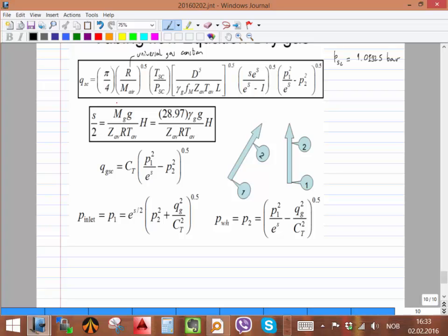So when you say that the gas flow is always turbulent, then the friction factor becomes only a function of the roughness and the diameter. And for tubings, usually from the manufacturing mills, there is a relationship between diameter and roughness. For a certain diameter, they already have a certain expected roughness. So if you put that relationship here, that gives you the relationship between the friction factor and the diameter, so you can make some simplification here.